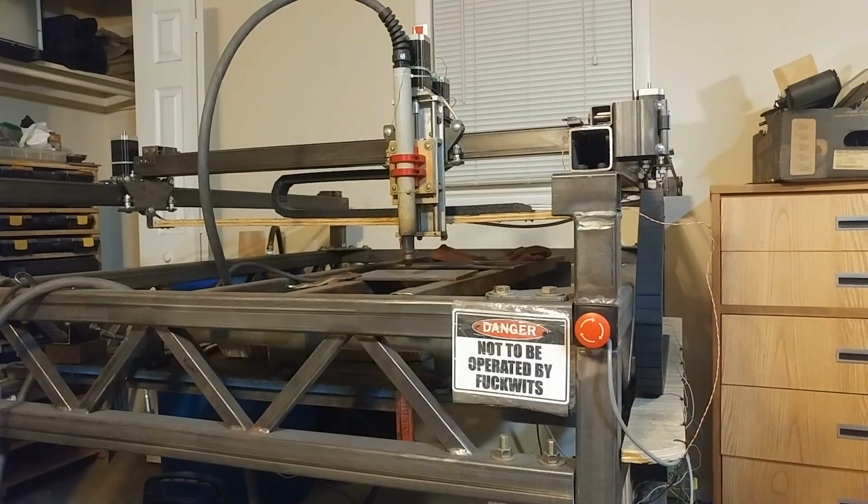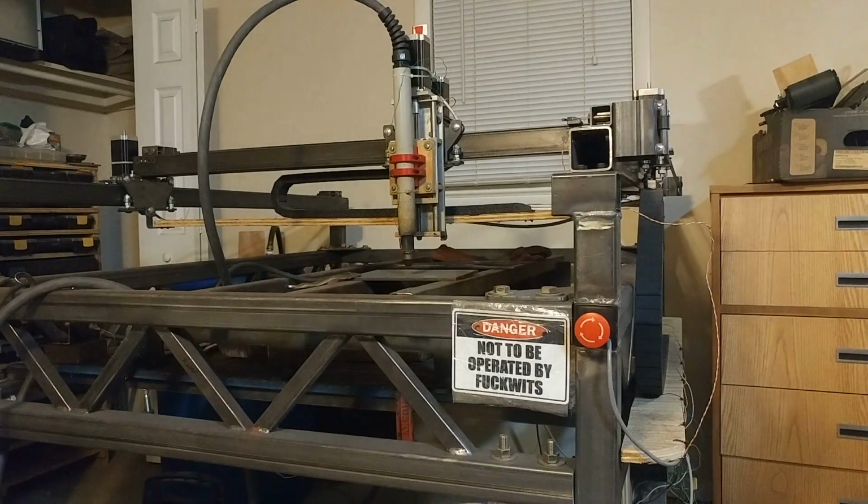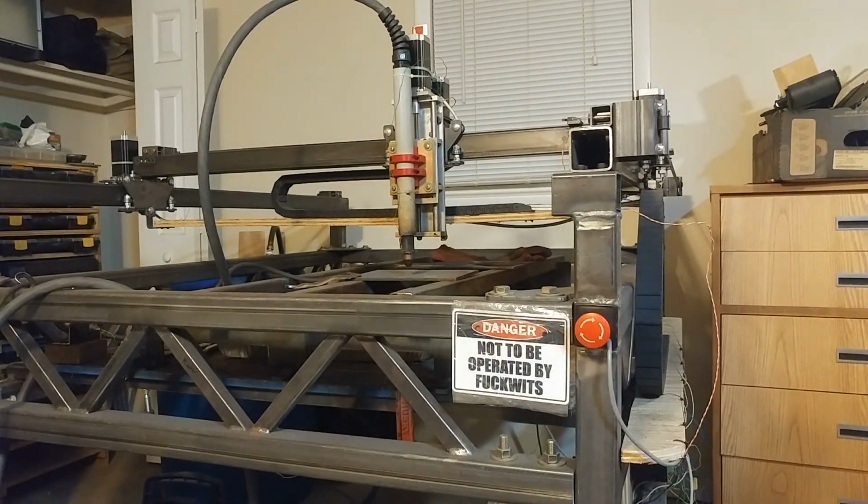So I'm going to load up a sample G-code, and it's just going to go out in one move and back in another. And we'll see during both moves, the jogging up and down are disabled. But during the return move, when M3 is turned on, we'll be able to use manual torch height control with these 2 buttons to jog the Z up and down.